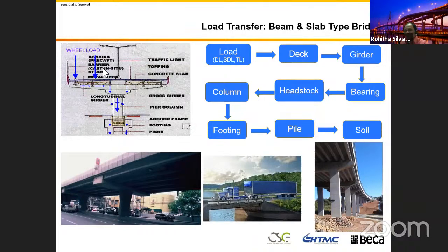In addition to that, the traffic load. Together with the other loads, like creep, shrinkage, thermal expansion and contraction, earthquake, flood loading, you name it. There are so many loads applied on the bridge. But for the bridge deck mainly, the dead load we call superimposed dead load.